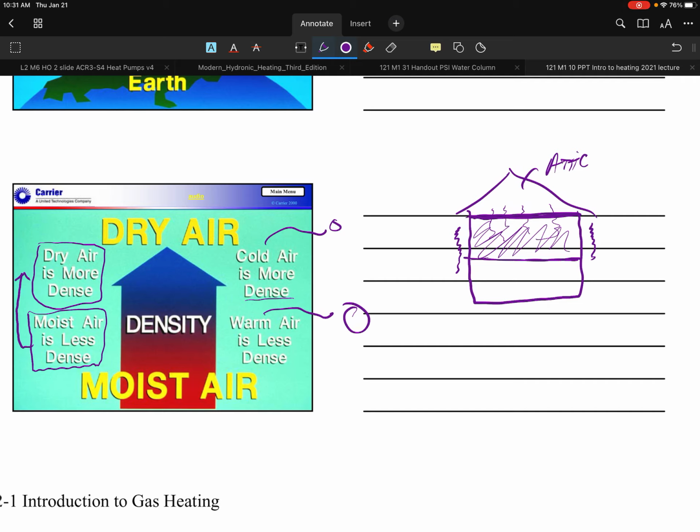Now, commercially, this is what I ran into on commercial jobs. They typically would have a false ceiling, which could be a bunch of 2x2 grates or 2x2 ceiling tiles, like you see in our classrooms. When we had issues with duct sweating, we looked at the air up in that space and the air in the lower space, and we noticed that the dew point was higher in the false ceiling than in the bottom part, simply because of this fact.